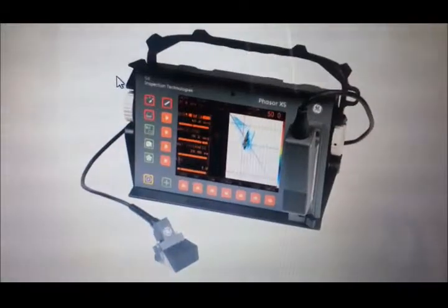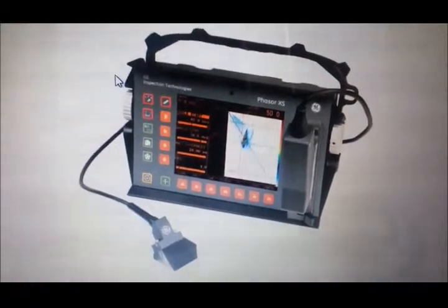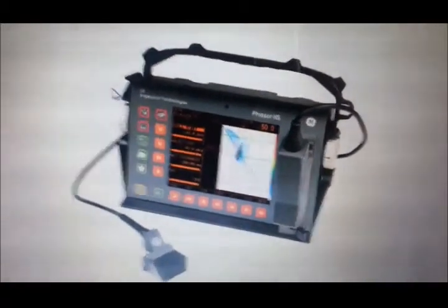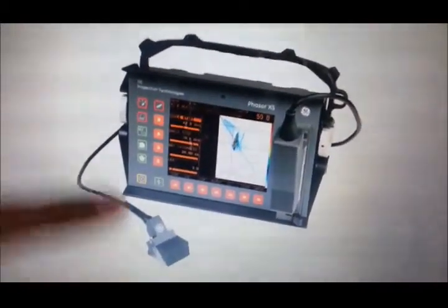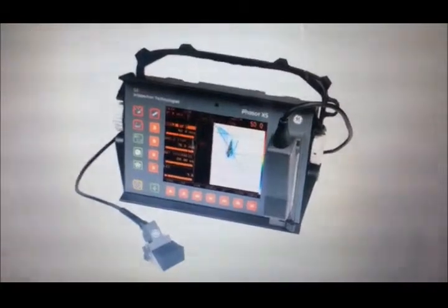Hi, my name is Bisham Ambra. Today we are going to do the experiment, which is ultrasonic non-destructive testing, and here I'm going to explain the procedure and how we have to do this with some coupling oil and a sample piece, and so we are going to perform this. So I'm going to tell you the procedure that we have to perform this experiment. So we have here a transducer, and this is our flaw detector machine.